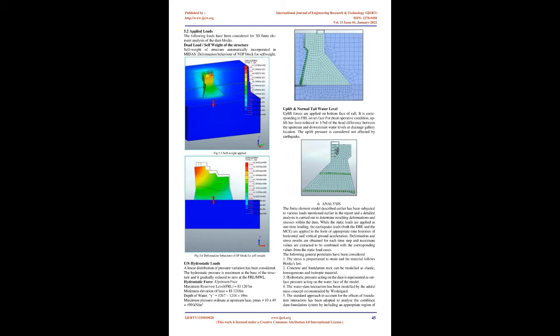5.1 Support conditions. For dynamic analysis, it is recommended to use semi-unbounded foundation and fluid domains with appropriate radiation conditions at the domain boundaries to allow propagation of outgoing waves. To simulate it, viscous boundary dampers can be provided in MIDAS. However, reactions to be used in stability analysis could not be obtained for these viscous restraints.